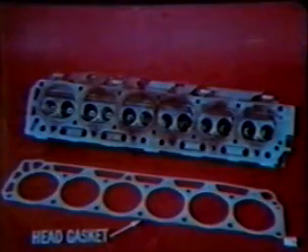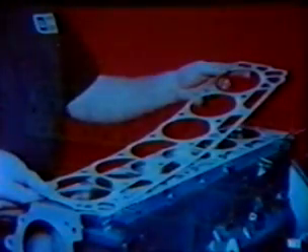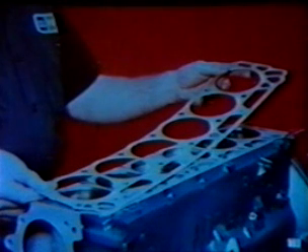The cylinder head is mounted on top of the block with a flat gasket, which seals the combustion chambers and water and oil passages from each other, and also from external leakage. It's customary to replace the head gasket each time the cylinder head is removed, since this sealing is so critical. Also, there is a particular sequence for tightening the cylinder head bolts to assure a good seal.